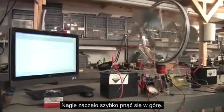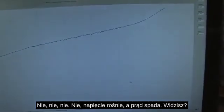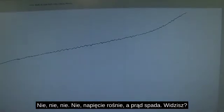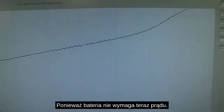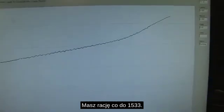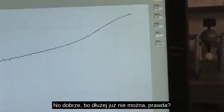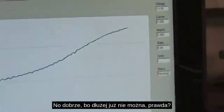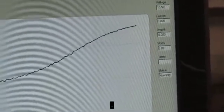It's suddenly climbing up rapidly. So it's more like a forced charge now? No, no. The voltage is rising and the current is going down. See? Because the battery is not requiring current now. You're right at 15.33. See, now it's going to start to bend over. Okay, because it can't take any more, right? Right. The chemical can't absorb it. And 15.5.